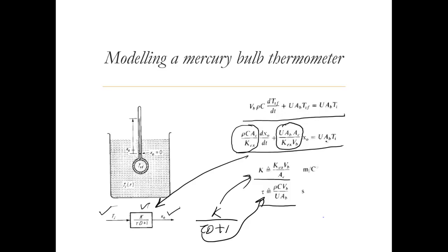So all those things are actually together, and then this actually gives you the governing relation between the input and the output. So Ti is nothing but the input, which is the measurand, and as I have told you, this is related to the measurand, and this is related to the instrument itself. All right, so these are the properties of the instrument, where rho is the property of the instrument, which is the mercury density.